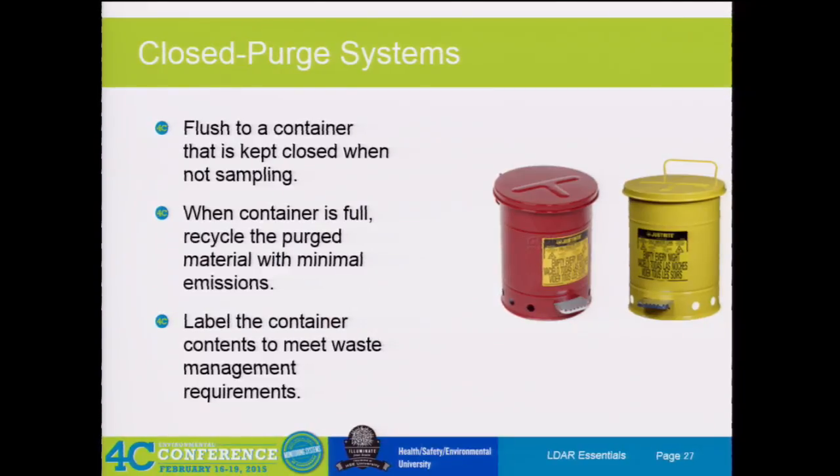Yes, it doesn't have to be identified in your system. It doesn't have to be monitored. It doesn't need to have anything along those lines done unless you see an AVO or something similar. Then most folks will put it in their system just so they can track it that way. And you can also go out and prove that it's not leaking above any leak definition, to show that it's below NDE, which is 500 parts per million. And NDE is no detectable emissions. And then it can be handled that way too.